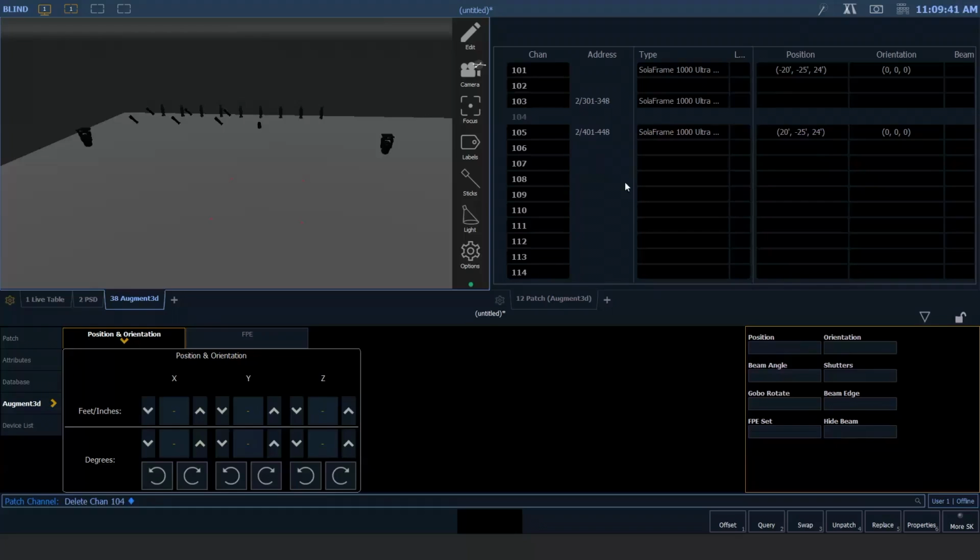All right. Invert pan tilt, does that affect the augmented? Yes, it does. Sorry, just to touch on that for one more second. The invert pan tilt, that's an example where, and I've had this experience in real life, where the model was moving opposite of my real life. So inverting there doesn't help because then they're both just going to swap. So that's the case where you need to physically rotate the fixture 180 degrees, and then that can solve that problem. Yeah, that makes sense.